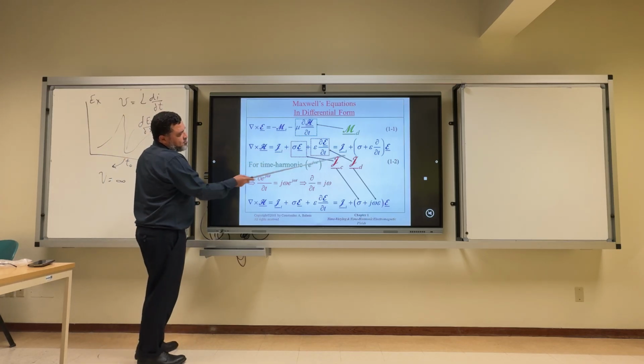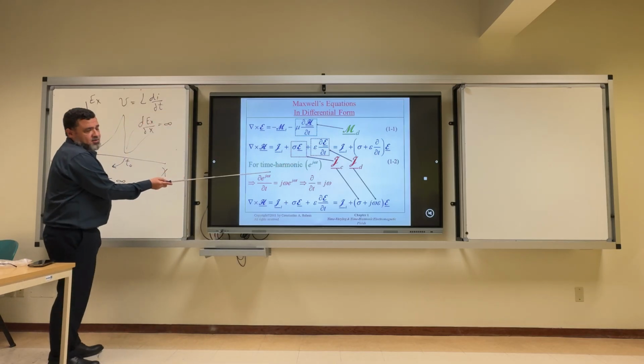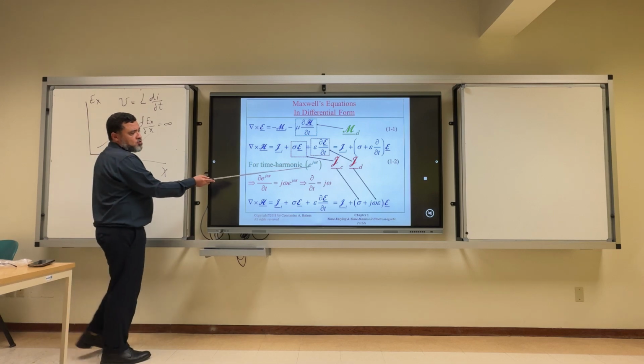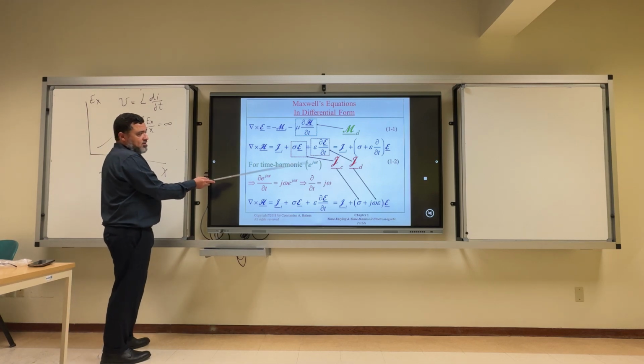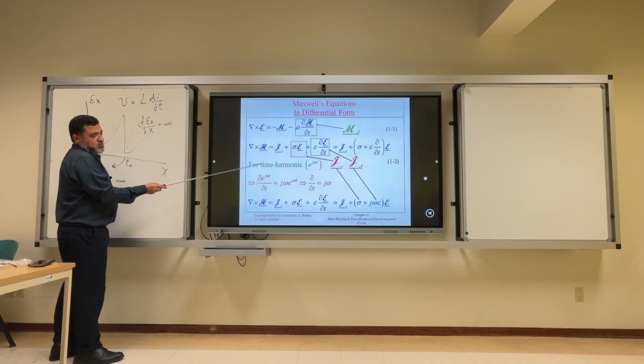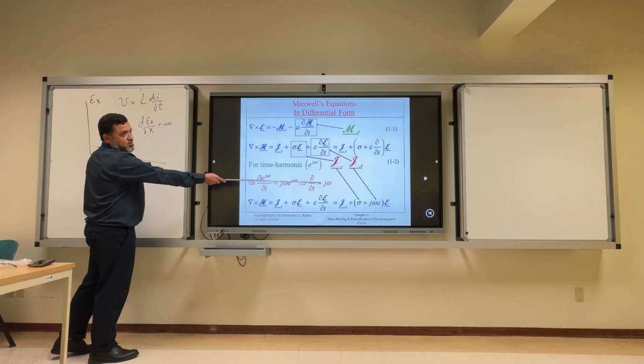And this is the displacement electric current density, as we know. We can now use time harmonic fields, assuming the field changes sinusoidally with time, so it will be proportional to e to the power j omega t. Then we use the phasor domain. In phasor domain, the derivative partial t of e to the power j omega t is the same as multiplying by j omega. So we can replace partial t by j omega.